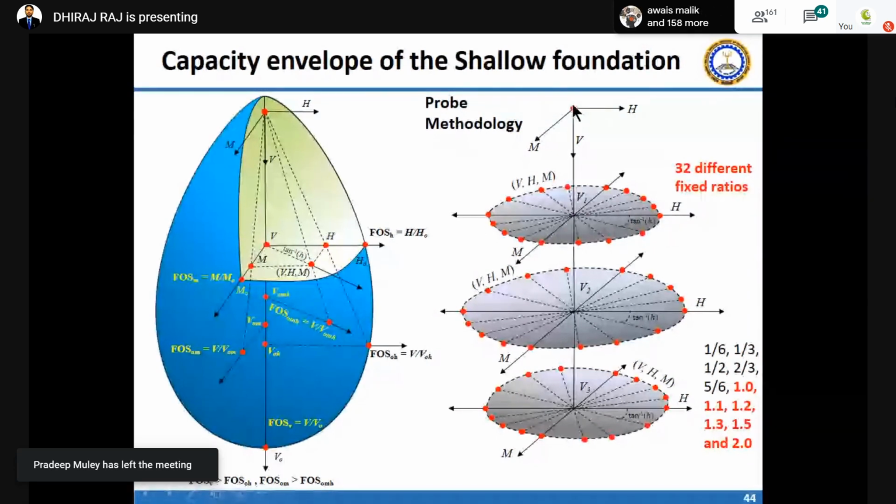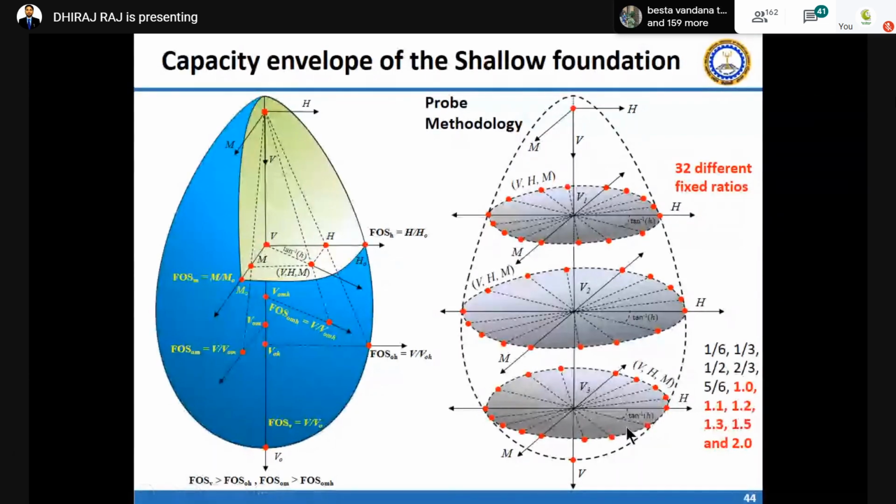And then at the angular load, we have simply combined all the points with a surface, and you will come up with this generated surface. So it's a complicated method, but in the case of complex foundations, we have to generate it. I will show you an example where it is very important. If you ignore it, you will come up with the wrong foundation size and other things.